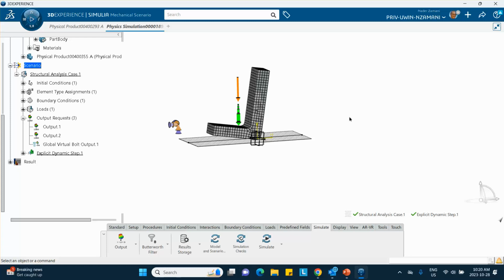and that's why I'm not going to even show you the stresses. Remember, in these tutorials, I am not discussing the validity of the results that I'm generating because I'm using some data from others. And I'm not doing any mesh convergence study. There is no guarantee that what we are doing actually is accurate as far as discretization is concerned. So just keep that in mind.